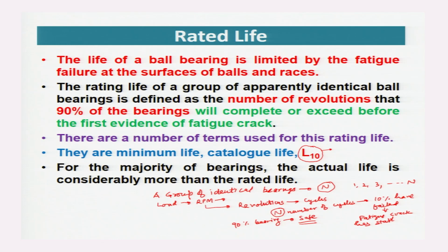So it may be found that for a particular bearing, the number of revolutions till the first evidence of fatigue crack will be more than this rated life. But as fatigue is statistical in nature, this rated life is taken for selection of the bearings.